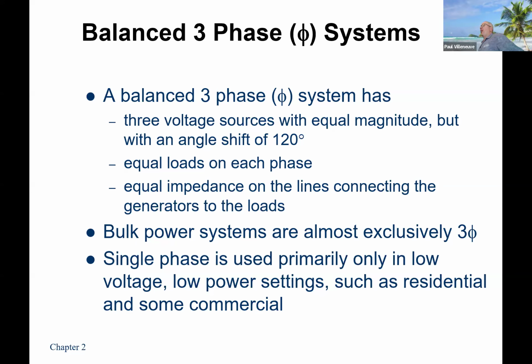That used to be the most common way to get power into a building because I can run a lot of power at 4160 with very small cables. But if the whole building were at 208, I'd need to run much bigger cables to distribute the same amount of power. So it's more cost effective to run as high voltage a cable as you can until you actually need to distribute the load. There's one tiny problem with that concept. Anybody want to guess?